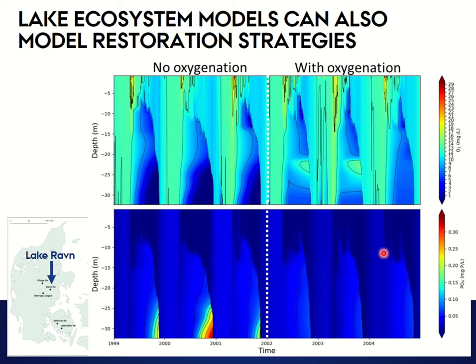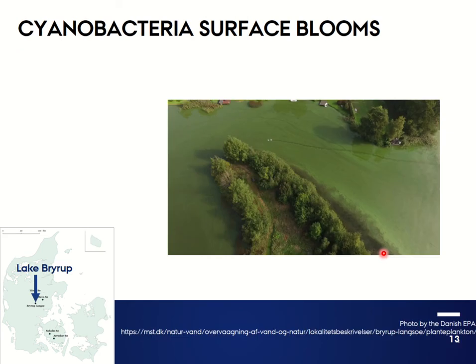As we see, the hypolimnion phosphorus concentrations are high each summer, but in simulations with oxygenation at around 22 meters, the hypolimnion oxygen concentrations are increased, which prevents release of phosphorus from the sediment. And simulating oxygenation is just one of several new model developments for the WET model.